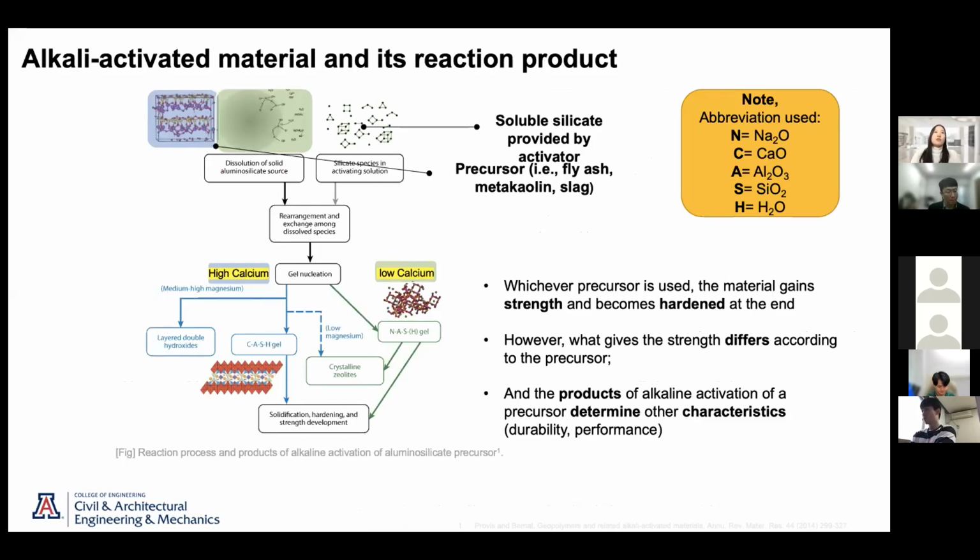SCMs can be used as precursors. Whichever precursor is used, it gains strength and results in a hardened material at the end. However, what gives the strength differs according to the precursor, because the alkali activation products of a precursor determine the physical and chemical characteristics.